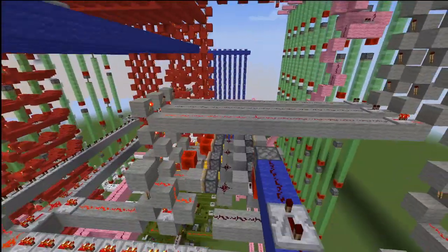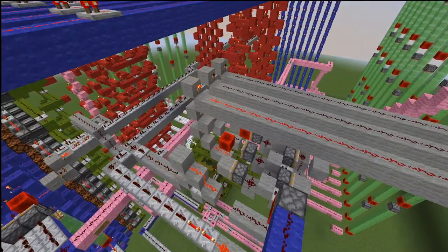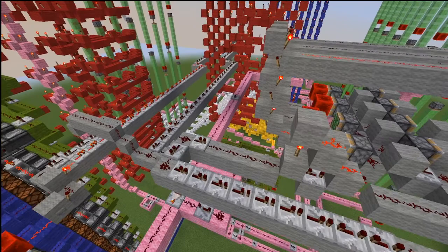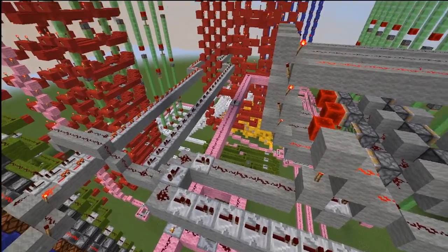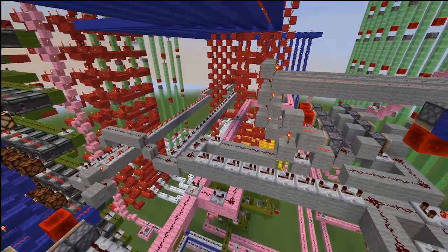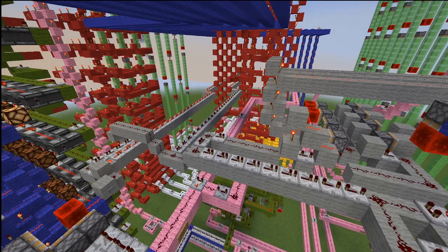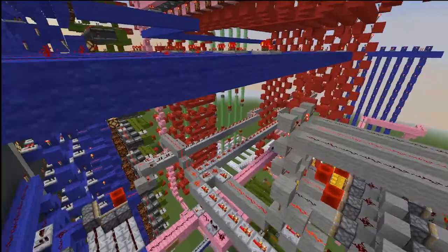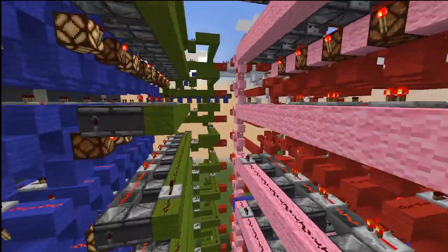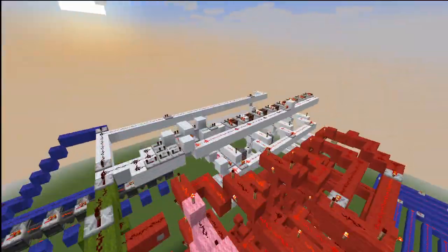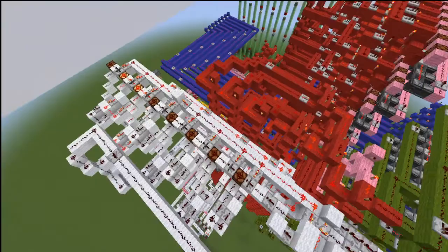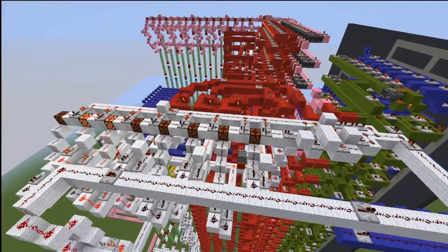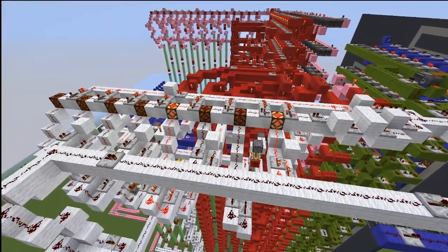So let's see where we are. Okay, on the next clock pulse, which should be coming in soon, it's going to start the macro instruction for out. So there it went. So we're going to start by, again, reading from the program counter, which is going to read a 9, because that's what's currently in the program counter.